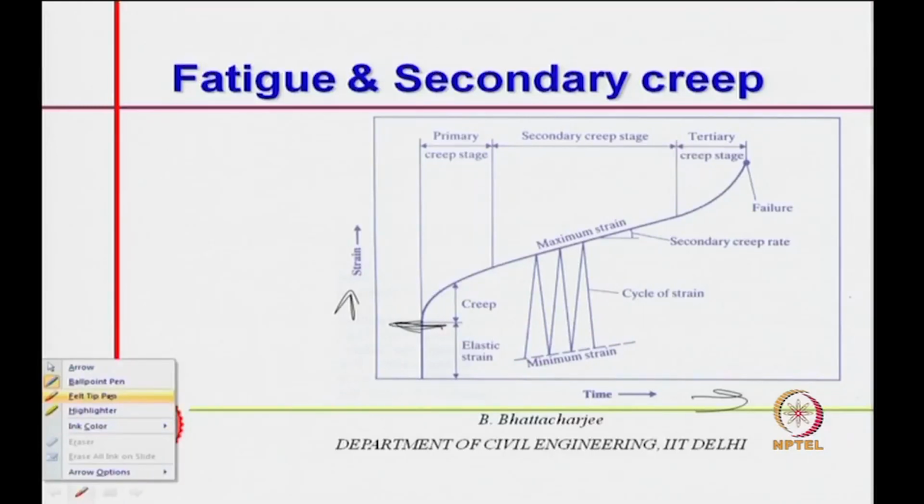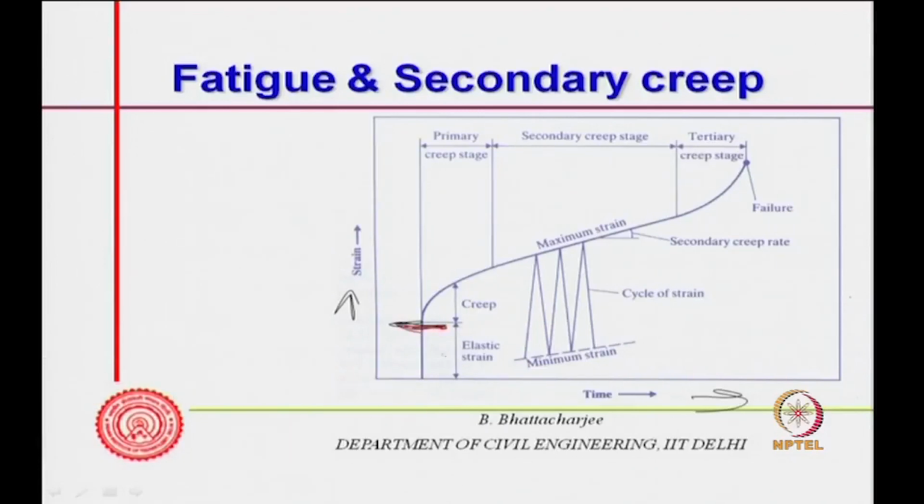Then there is creep, but beyond a certain stress level, this goes on increasing. We have seen in the case of concrete, of course, at normal lower load levels, it tries to be asymptotic, but in many materials the slope gets reduced, and it is like a linear constant rate increase.